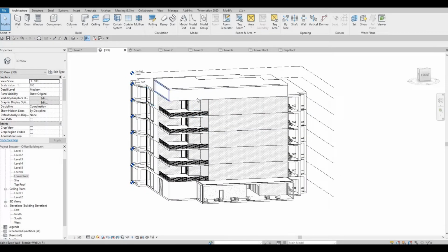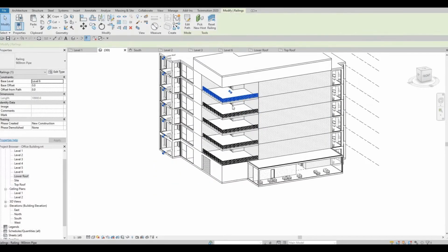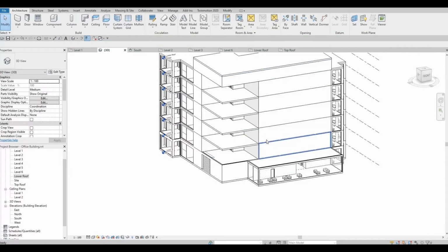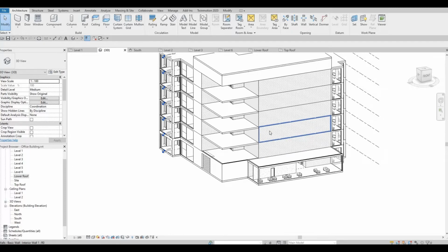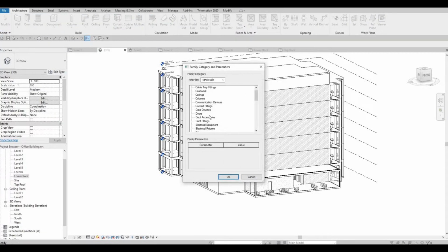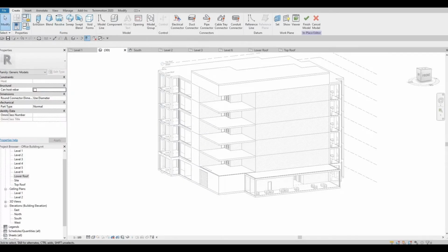We will extend this a little bit once we create the design. But I'm planning to remove all of this. So the design will be one big one right here. So for now, I'm gonna leave it like that. And I could create the model in place now. Generic model, press OK. Generic model number 1. And then extrusion.